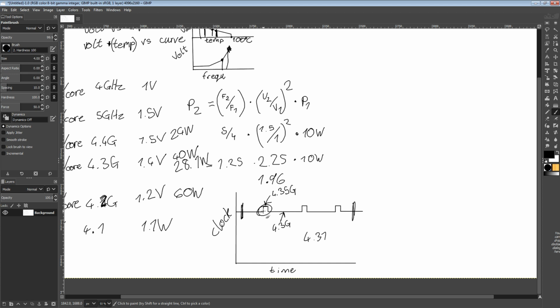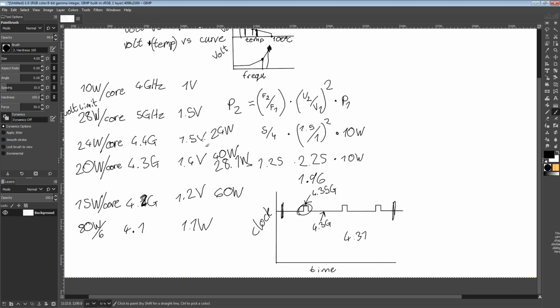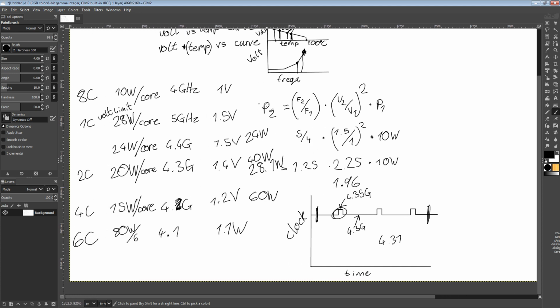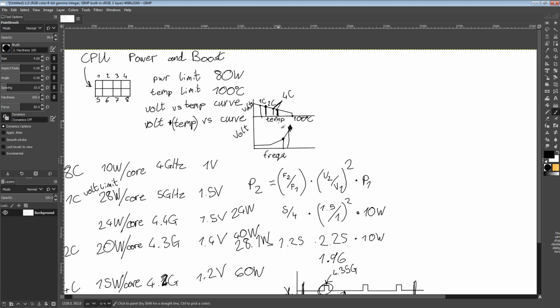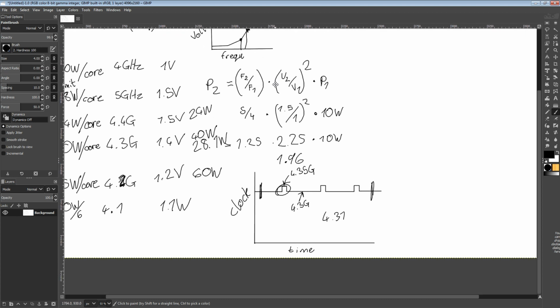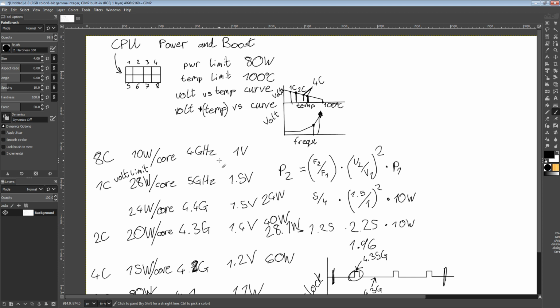If Intel had AMD's boost algorithm, Intel would be shipping 9900Ks with a 5.5 gigahertz boost, or like a 5.4 gigahertz boost. The other thing that's kind of cool about the algorithm is that, because your max safe voltage changes based on operating temperature, at low loads you can run really high voltage, because the temperature's so low, we can smash the voltage for days. The side effect is that at low loads you also get really high per core temperatures, because you're smashing all of that power into a very small space.